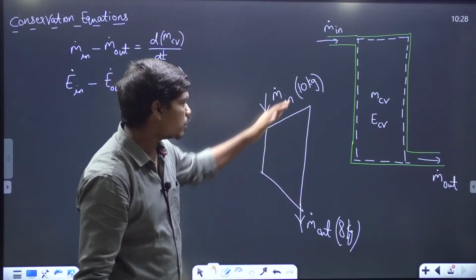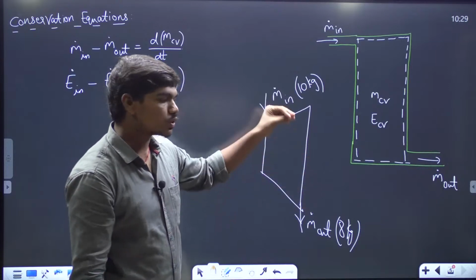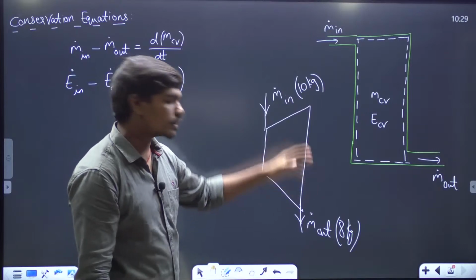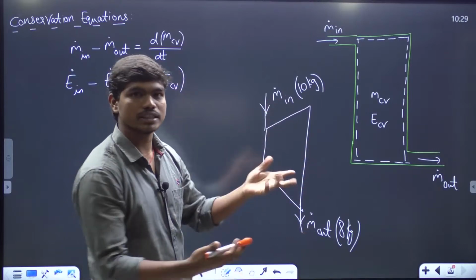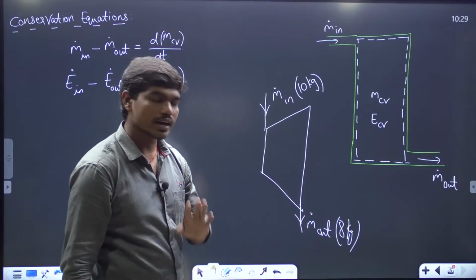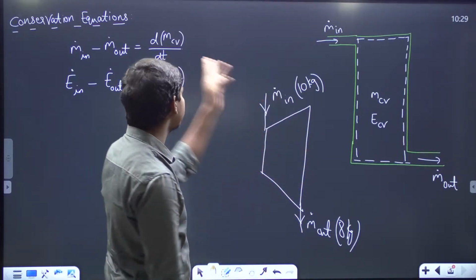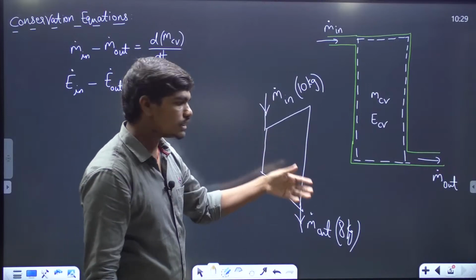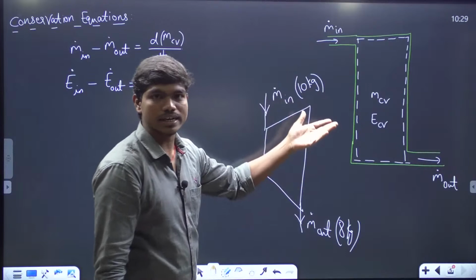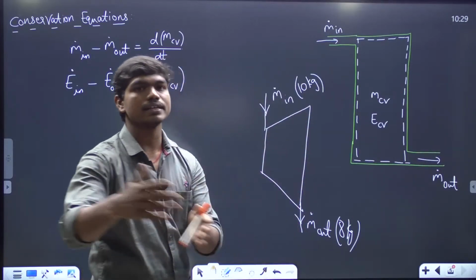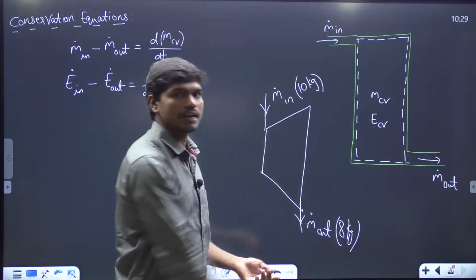Correct? And you know the volume of this turbine is finite. So after some finite number of cycles, this turbine gets blocked. Correct? Because it is completely filled with mass and there is no room for new mass to come inside. So generally all steady flow energy devices operate in steady state for mass, because they don't need mass accumulation inside. Similarly, outlet can't be more than inlet, because if that's the case, power automatically starts decreasing, and after some finite cycles there won't be any mass left within.